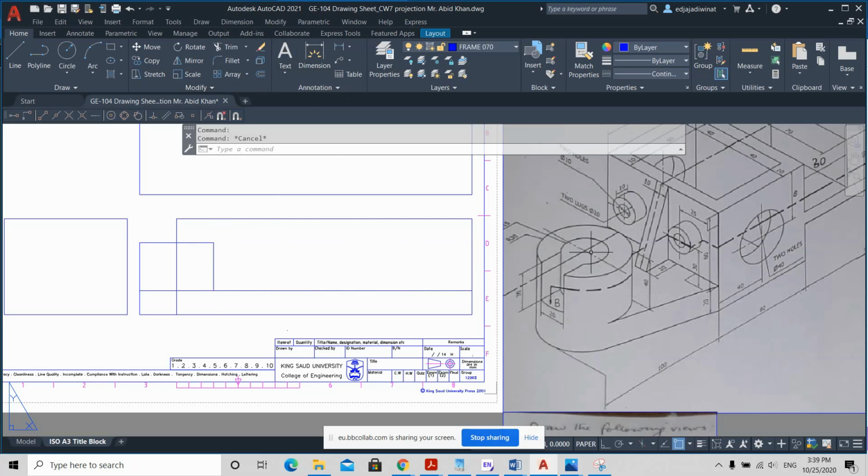Next, let us make the circular hole. So I will use offset again. And I know the cylindrical hole here is 15. The radius is 15, so type 15. I'll offset to the right, 15 to the left. There. I'll trim like that.